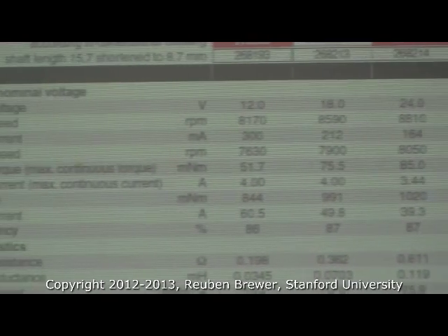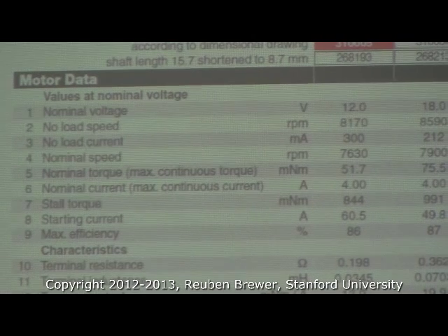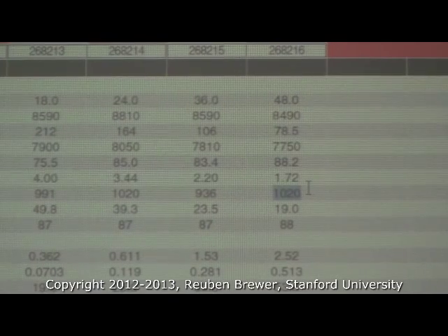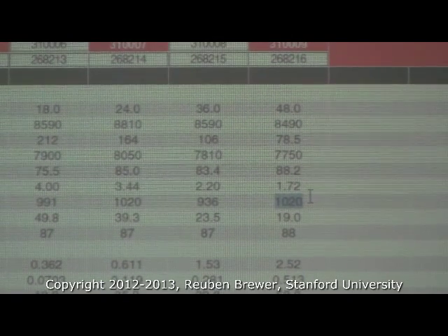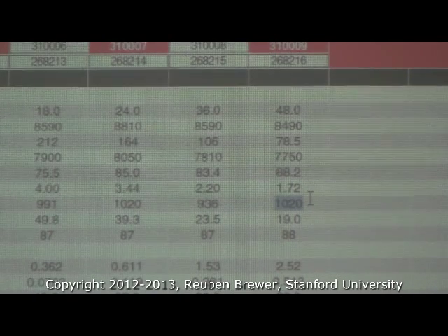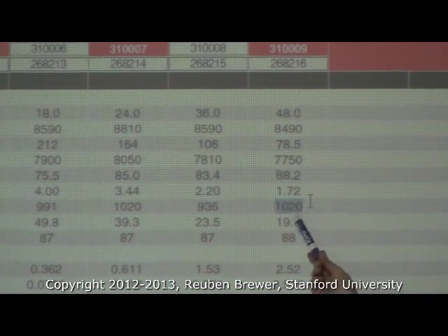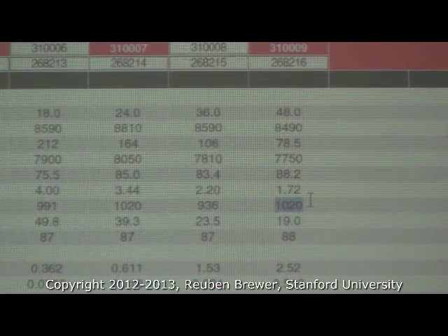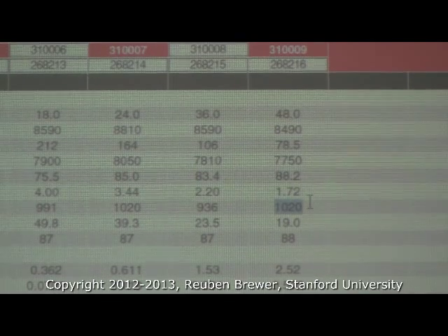Too bad. The only time you often really have to do stall torque to get their performance is with haptic devices, in terms of what I've done. There are lots of reasons. Let me suffice it to say, you can drive at stall torque, which is called peak current. Peak because you can't exceed that, for very small fractions of time. We're talking like 1%, 5%.